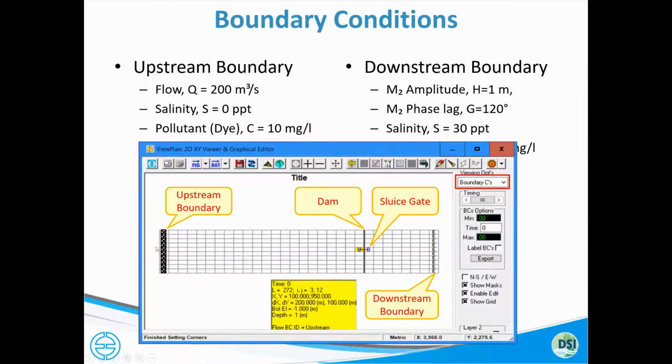So we'll build it. This is the grid, and this is an example screen capture from EFDC Explorer during the construction of a model. You have the model domain, the model grid, and these boundary conditions as indicated by these check boxes. For the upstream river, you have the tidal boundary on the east edge of the model domain, as indicated by these E's in the model grid cells.